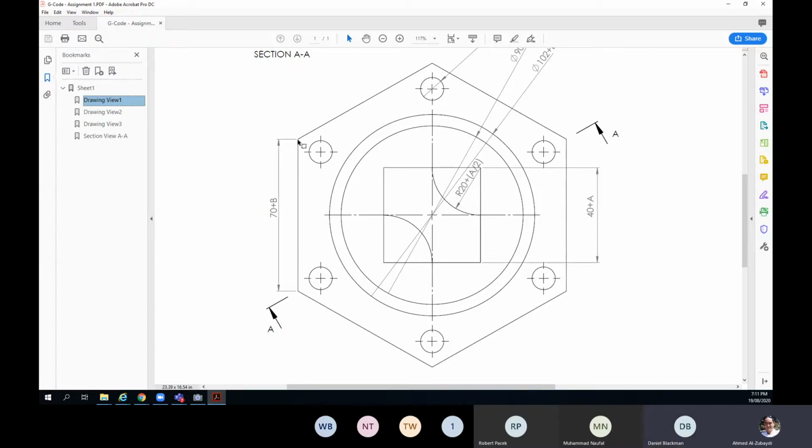Then if I make a perpendicular line here, this will be 90, and the rest is going to be whatever the value is minus 90 degrees. And first we'll be able to find this side: multiply the sine of this angle by the length of this side, and we will find the vertical height. So I'm sketching something on my paper. I'm going to show you what the total height will be and where we are going to use it. Okay, so I will put the maximum value, alpha, because this is how we are going to start to find the dimension of the original part we're going to start the machining of. Okay, so now this will be the shape.